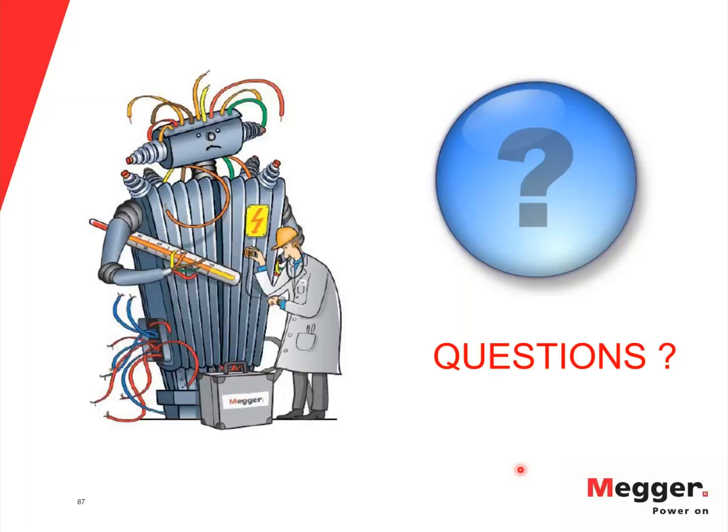If you are doing an operation in the field, and let's say that you don't have an LTC, a load tap changer, but you have only a DETC, I would suggest you to first ask the operations owner and discuss if that DETC has been exercised before. If the unit had the DETC in one position for a long time and that DETC has not been exercised, I wouldn't recommend you to move that one.